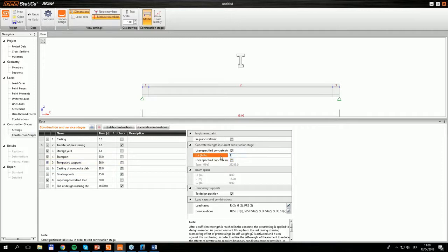And this situation also allows you to input concrete younger than 3 days. Once we do that, or uncheck that, you can see that the software warns you. Now we have the possibility to input the elastic modulus. So in the same way, let's say 30 gigapascals, and it's all recalculated based on these data.